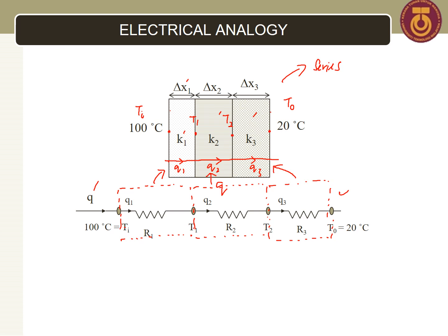After this, almost every time when there is a heat transfer problem, you need to translate that system into a circuit diagram like this. It will enable you to do the calculation much easier.